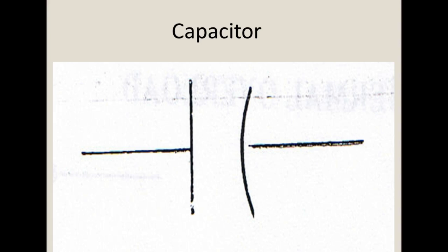Our second auxiliary winding, it might be here in time. It's out of phase. Now, anyway, this is not the motor class. We have to understand something. We want the farther out of phase, the more starting torque this thing has. So we take a capacitor and we put it in a can.